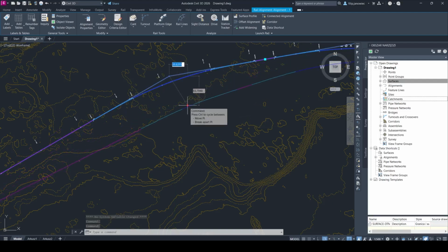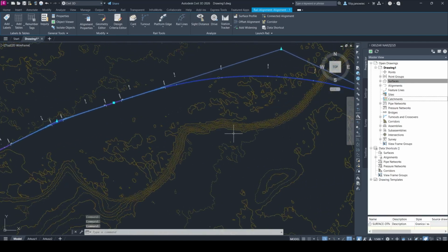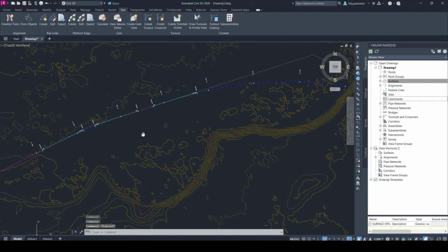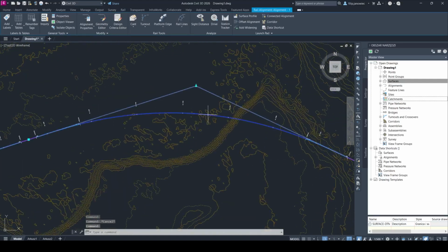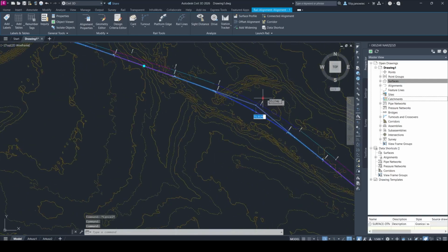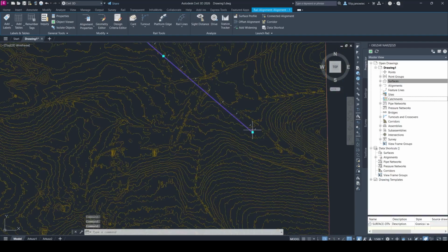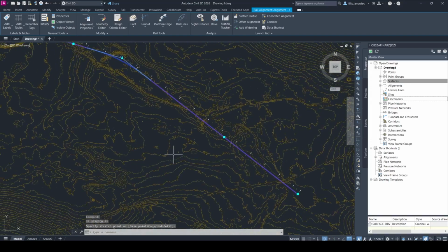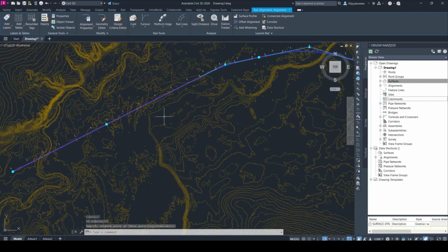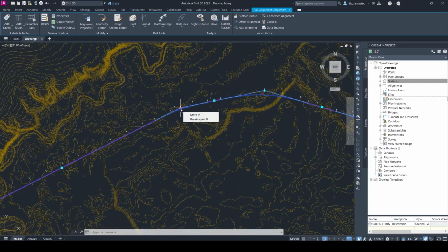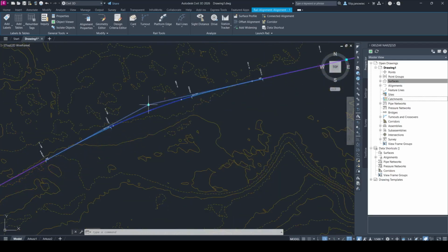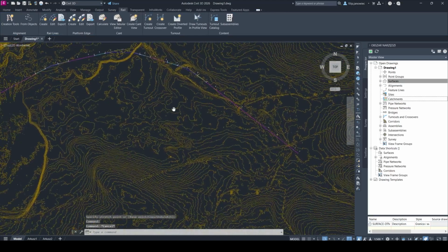This is the Civil 3D big advantage, because after defining some curves, we can adjust them to, for example, our terrain, and we can edit it by dragging some points. Also, we can choose the start and the ending point, but I think most of you will use it by moving around some geometrical elements. It's quite good, as you see.